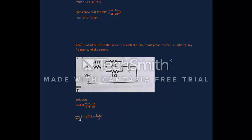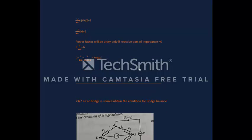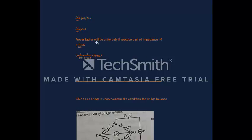We get after solving this, minus J upon omega C plus J4 plus 16J into (4 minus 4J) upon 32. If we solve this, the equation turns out to be minus J upon omega C plus 6J plus 2. So for the power factor to be unity, the reactive part of impedance Z should be 0. Therefore, if omega C is 1 upon 6, we cancel out the J component. Therefore, C is equal to 1 upon 6 omega, which is 1 upon 6 into 314.